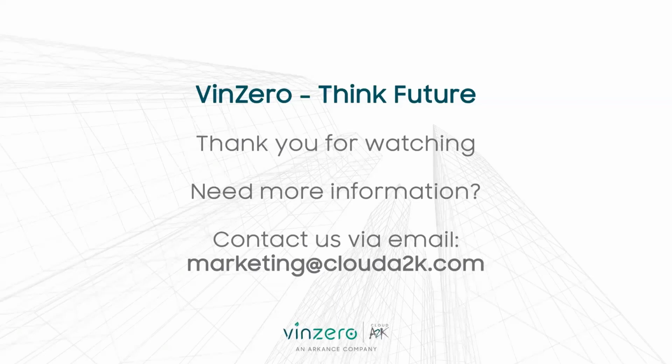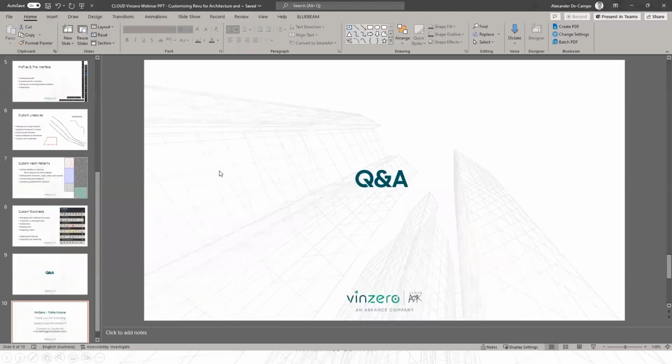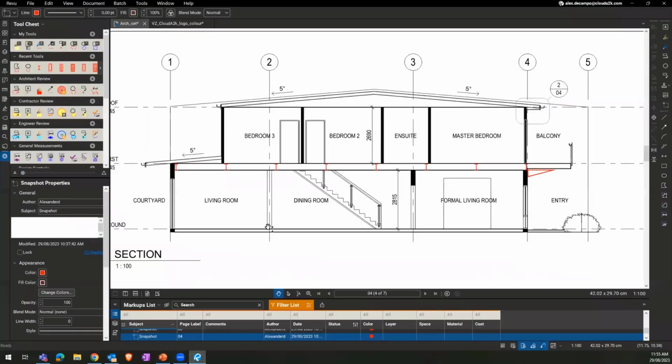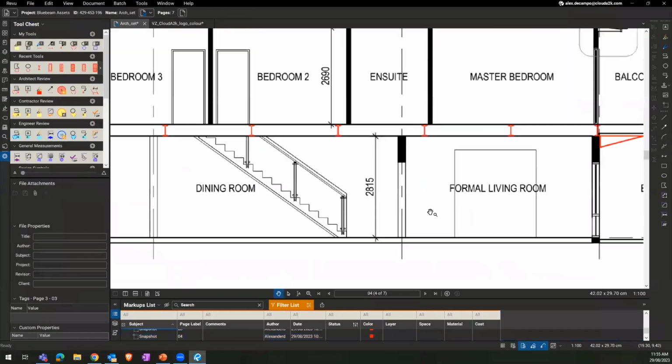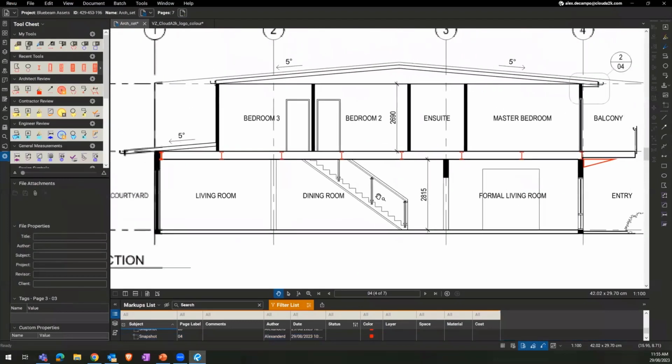Is it possible to distribute by set dimension of the floor joists? Could I set the internal at 600 spacing? So not exactly. If I wanted to do this with this tool, one thing you can do is do it in the reverse way: if you know the total distance you have to span and how many beams are going there, you can have it distribute.